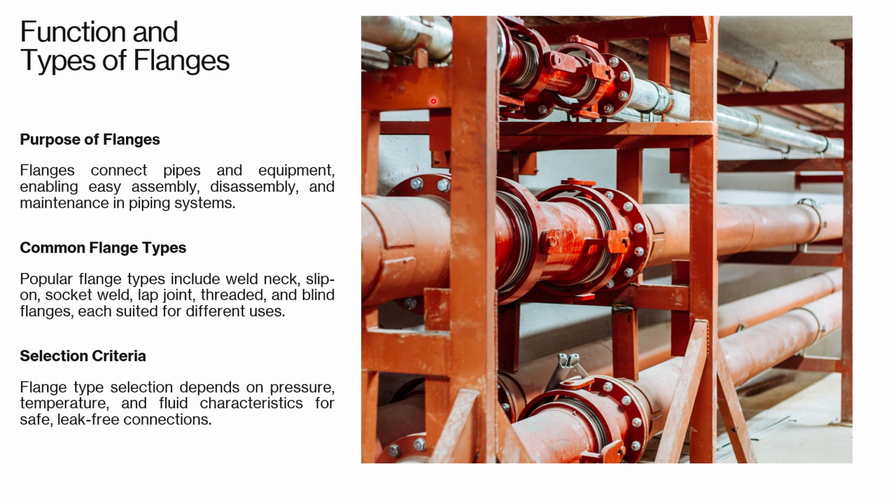So flanges, as I mentioned previously, are used to connect pipes. When we don't want to do welding, you can go for flanges. And let me tell you, most things like valves, pumps and other equipment all have flanges at their ends, and we connect them with flanges only. Flanges have a pressure class rating, which we call class 150, 300. Based on those classes we select the flange. Why do we go for flanges? They allow for easy assembly and disassembly, which is essential for maintenance and inspection. This is an important point, and people generally ask this in interviews.